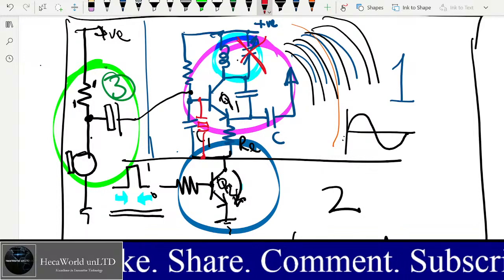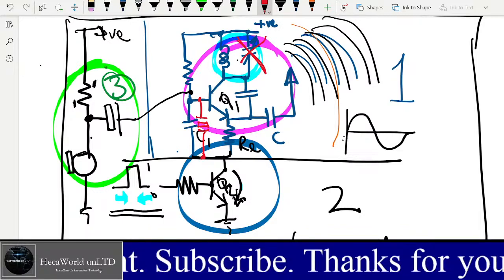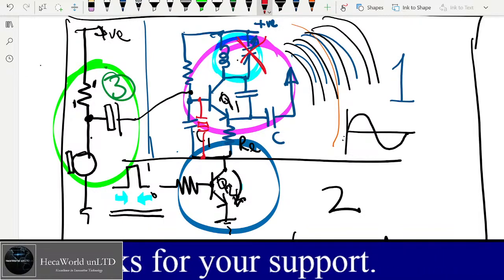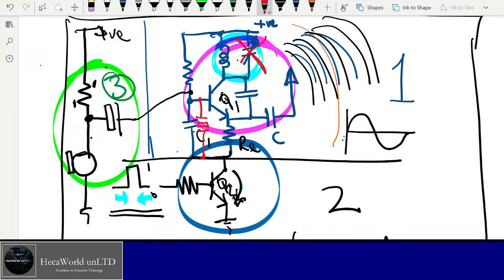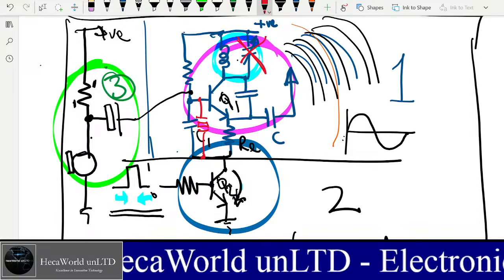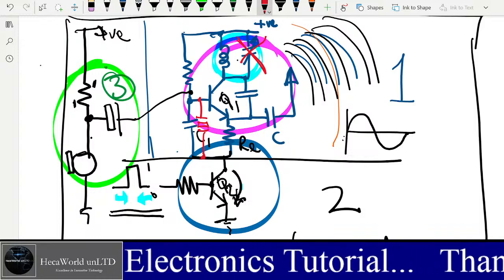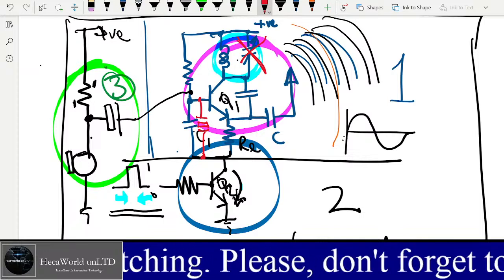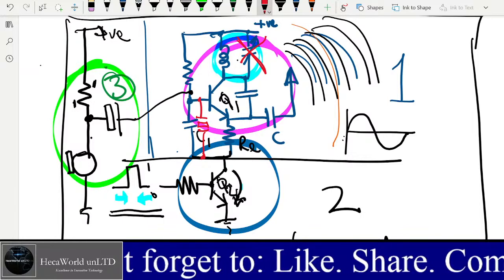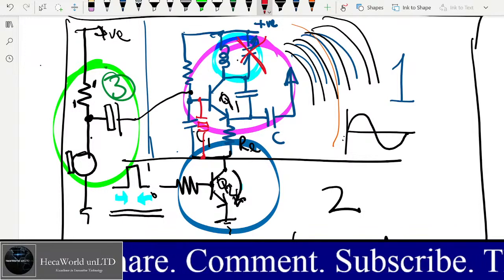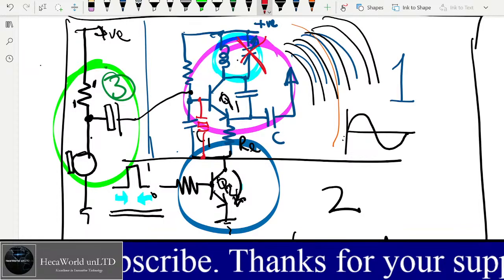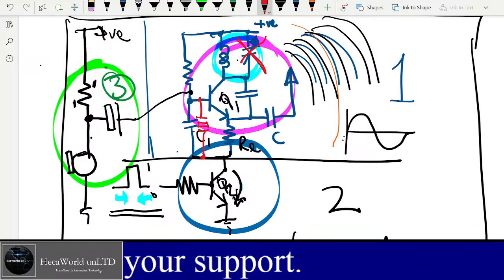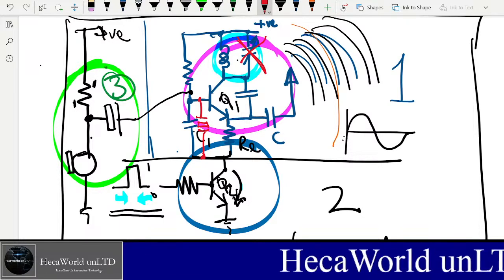So if this is a fixed frequency, then anytime you power it on, the frequency will be the same. This is important for remote control devices, because if you use the original circuit we have here with an inductor and a capacitor, it has a variable frequency that is dependent on voltage. So it's called a voltage controlled oscillator. When you use a voltage controlled oscillator, as the battery power degrades or reduces, the frequency changes, even if it's slight, but it will still change, right?